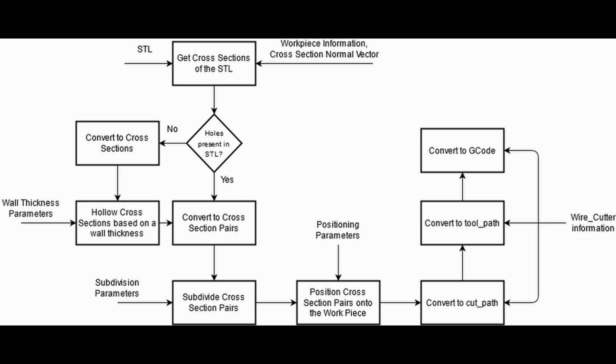So now you can position these smaller cross sections in a more optimal layout to better use the entire workpiece. Say a circle becomes just 4 arcs, well, those 4 arcs can be stacked on top of each other. In a way, they take up a lot less area on the total workpiece than if you just had the full circle, taking up the entire internal space that you're going to end up scrapping because you don't have a use for it anymore.